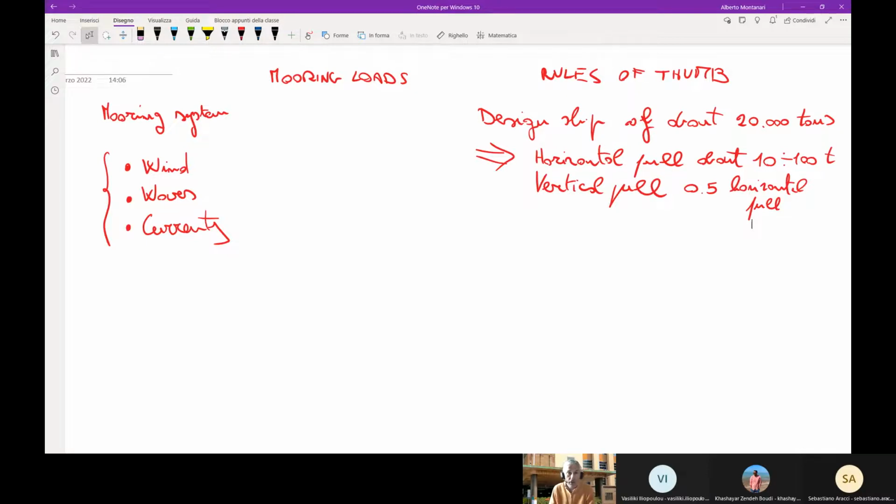I mean, if the structure is massive, extended, complicated, meaning that the design considers solutions of complicated structures, then we may need to be very specific and estimate the load at each mooring point and consider the overall load as a sequence of concentrated loads. But usually we talk about structures that are fairly oversized, gravity wall structures, structures that indeed can be designed with a simplified approach. And in many cases, as I said, we can consider the load as a distributed one.